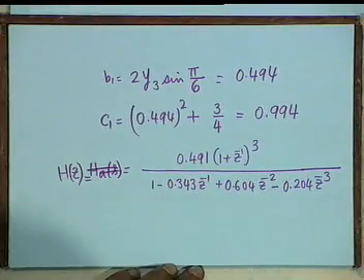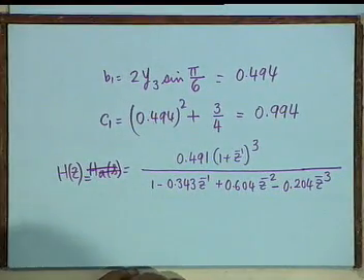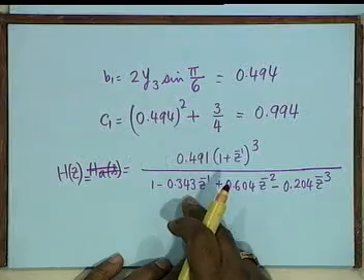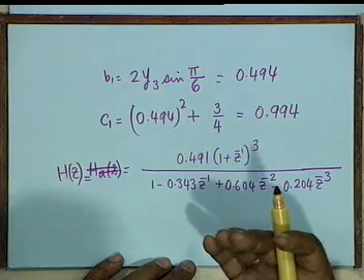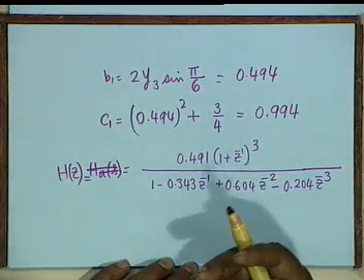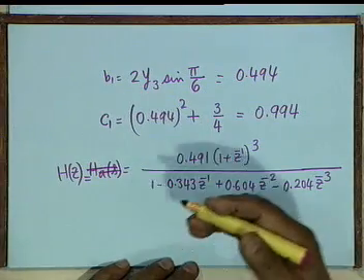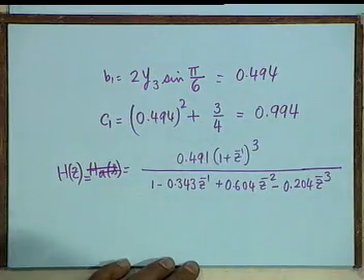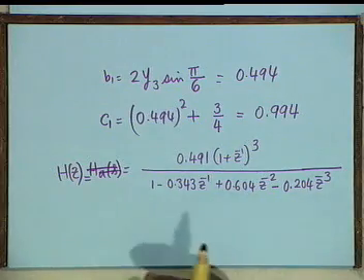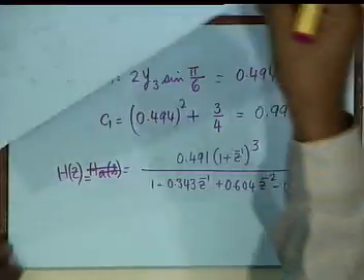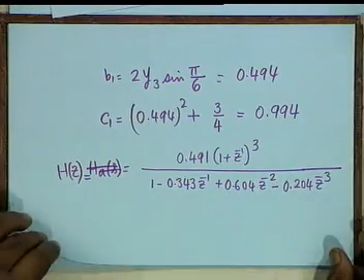Now it is up to you to put z equal to e to the j omega, find its magnitude response, and see how much is the deviation because of truncation up to the third place of decimal. You can also see, if you use MATLAB, then there is no problem. You can also see by extending the number of digits to the right how the error gradually diminishes. No, I didn't have the patience to program it and plot it.